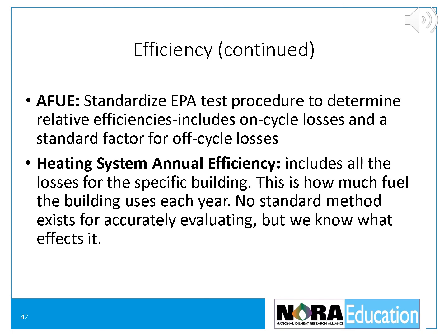Annual Fuel Utilization Efficiency, or AFUE. This is the U.S. government Department of Energy's attempt to provide a rating for boilers and furnaces. It is based upon standardized testing and calculation procedures developed by the DOE in the late 80s. Manufacturers must perform these tests on every model of residential boiler or furnace they sell. These AFUE results are printed on a yellow label that must be affixed to the unit. They are also listed in several heating equipment directories.